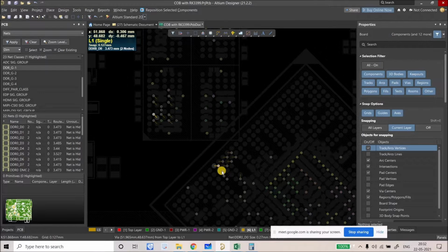As you can see, if you start from here, this will be connected here. Just do the layout in your mind without routing a single track. See how it will be connected. It should be connected from here to here. So I'm highlighting this using Control and click on the net. It will be highlighted, right? This will again be a very straight connection.